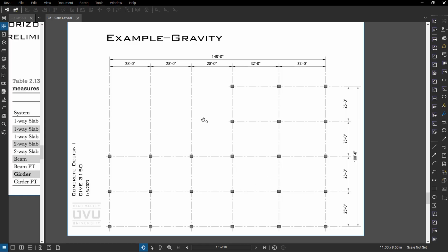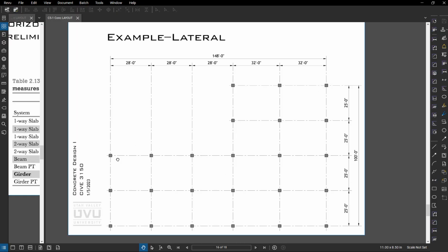Same sketch for the lateral system, deciding how you're going to lay out the lateral system of this building. Some people may want to keep everything on the perimeter and maybe just do something like this where they've got a couple shear walls, like maybe like that. I would encourage you, if you have a big jog in a building, to at least add shear walls on those free edges, and you can be creative here.